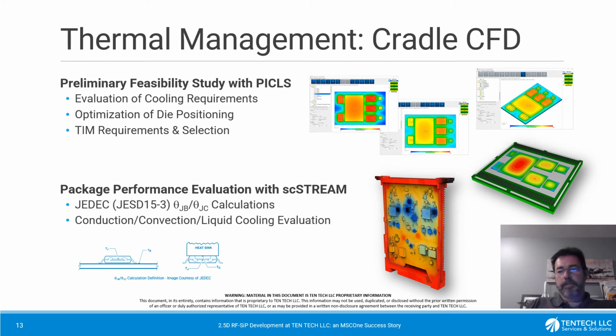Those allow us to provide a supplier, for instance, a set of values, thermal resistance, to plug directly into their thermal model without having us to provide anything but those calculations. This is a standard calculation, very easy to do in scSTREAM, and we perform that systematically and give those numbers to our customers or their customers to evaluate their final design.